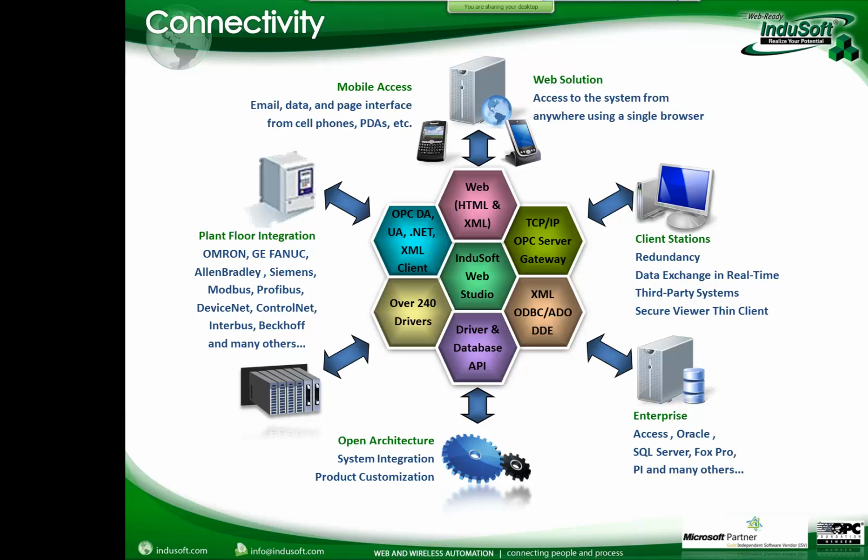So if you have an application that is an OPC client, it can connect to our tags database through our OPC server, okay? But we also have a gateway that connects to other SCADA packages, and we offer also our open APIs. Let's say that you are developing your project using .NET, for example, but you want to connect to InduSoft to acquire the values of some tags. You can get our tags database toolkit and acquire data directly from the InduSoft tags database.